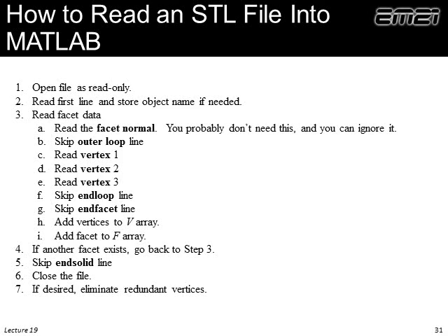Okay, now how do we read an STL file into MATLAB? And we know that there's things that we have to skip. We're expecting them. Things like facet normal, outer loop, vertex. Words we know that'll be there, but we can skip. And we know how to do that from earlier in this lecture.